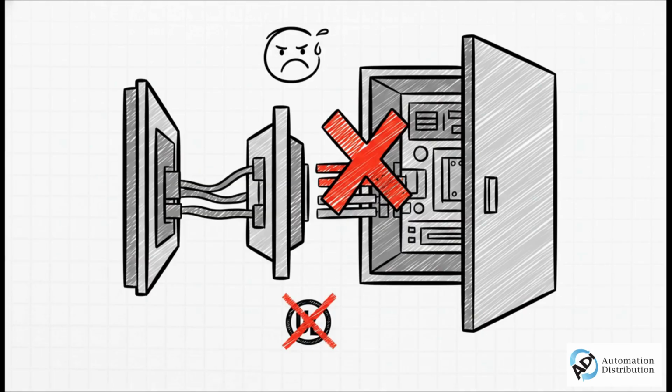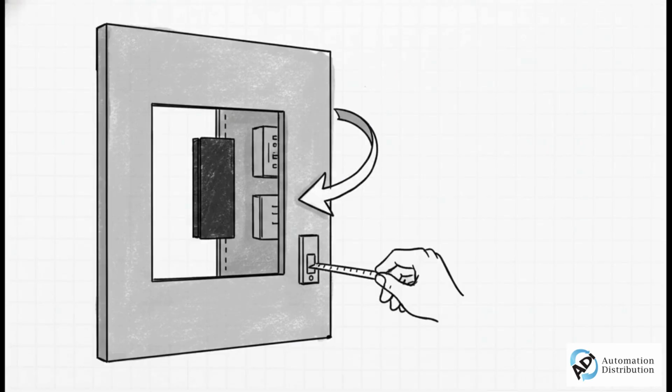It's a total nightmare. And get this, a door that won't close can actually cost you your UL listing for the entire panel. That leads to incredibly expensive rework and, frankly, ruined weekends. Fortunately, WAGO solves this headache right out of the box. These panels have an incredibly shallow depth. We're talking roughly 50 to 52 millimeters. That saves a tremendous amount of internal cabinet space.